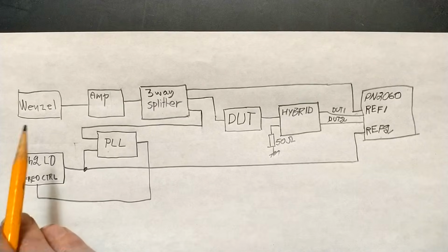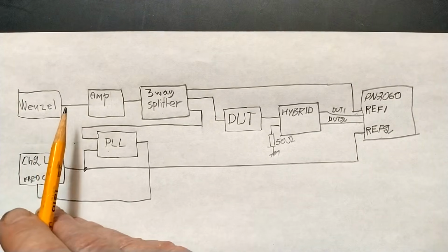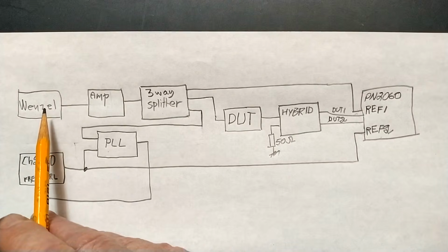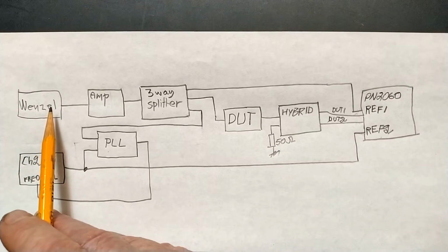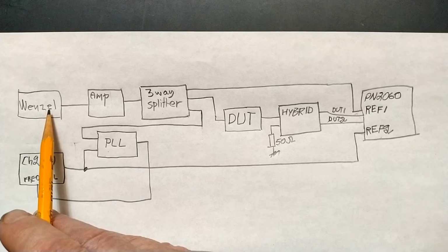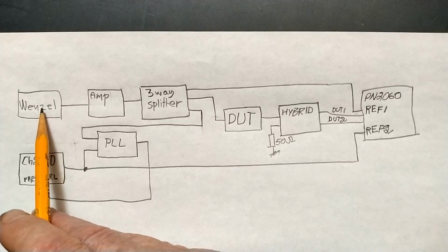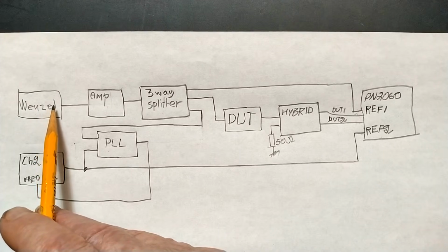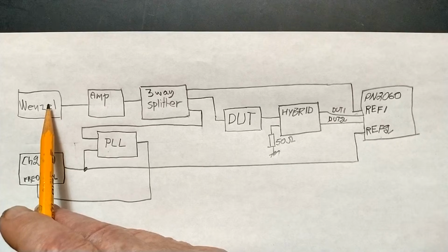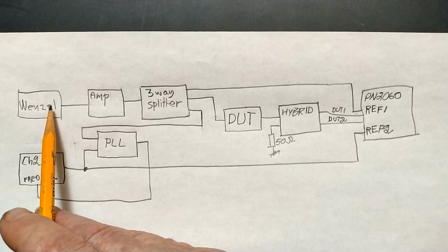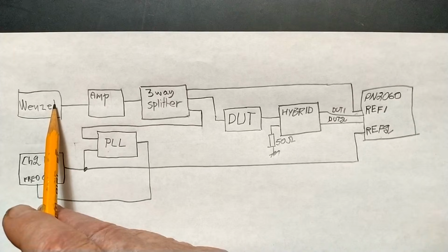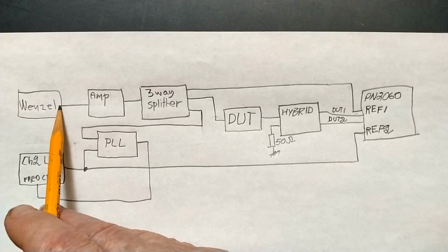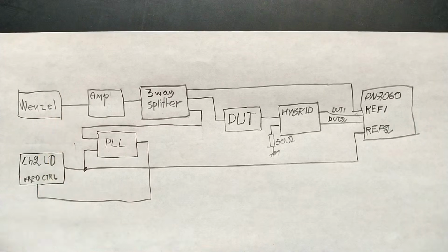For measurements through the crystal filter at frequency separations from the carrier below about 1 Hertz, the passband is so flat that the noise suppressed by the filter is negligible, down to something like 10 decibels. But at higher offsets, of course, the noise from the Wenzel is removed by the filter.